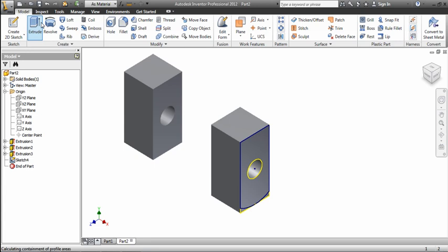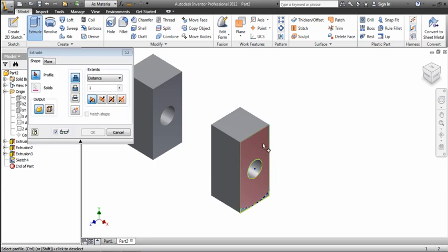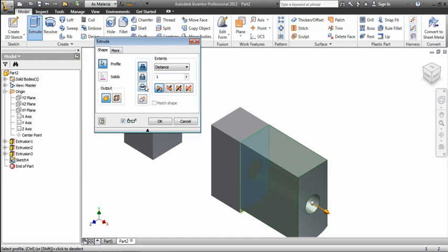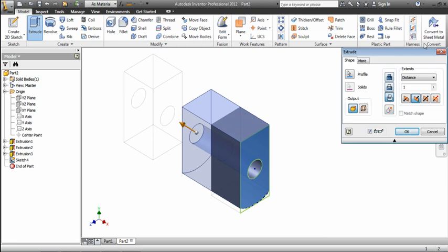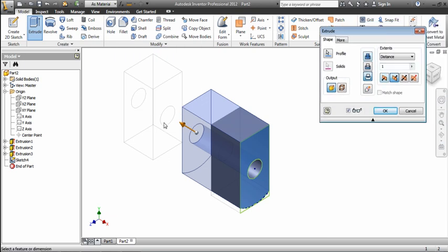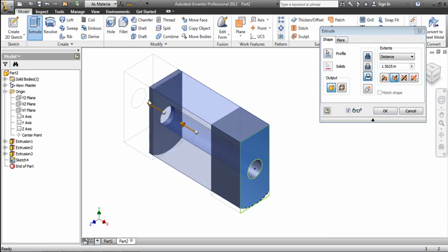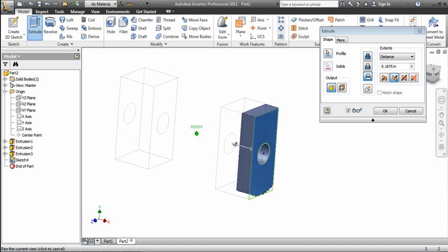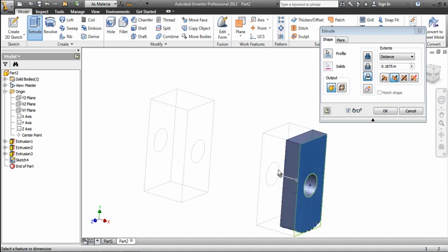Now, if I go to Extrude, and let's say I choose this, I'm going to choose Intersect as my extrusion, which is this third guy right down here, Intersect. What Intersect does is whatever this shape goes through, it's going to include, and everything outside of it it's going to get rid of. And so basically, if I only wanted that much, I'm only going to be left with this little sliver. All of this stuff that's kind of hollowed out right here is no longer going to exist.